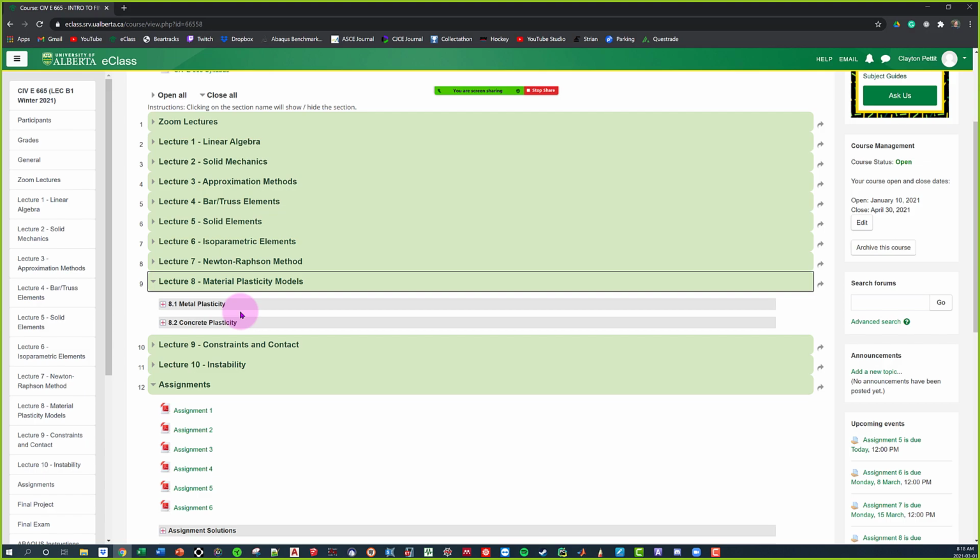What typically happened in the past is when our mesh breaks into pieces, you would remesh the object. As your analysis ran, you would apply a load, remesh the object, apply a load, remesh. But there have been some very nice advancements, called XFEM, which allows us to display those cracks.